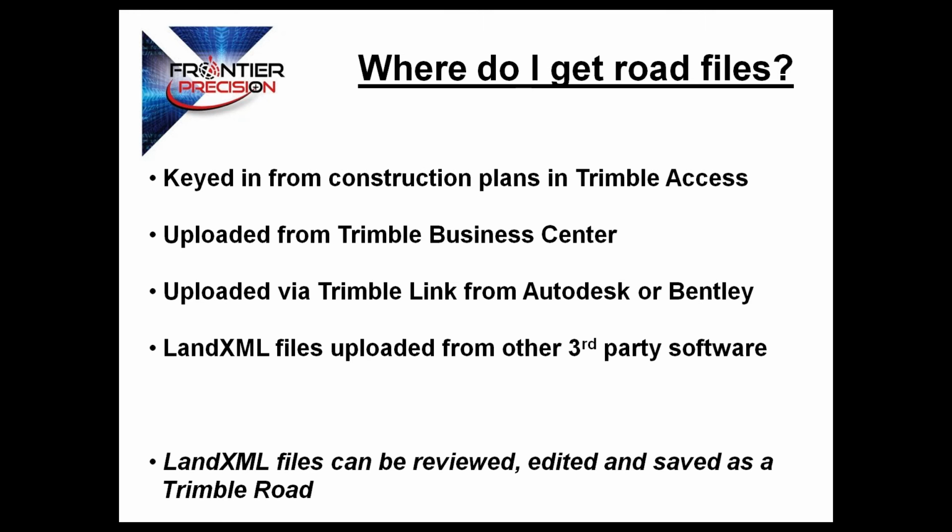Another little note on the bottom is land XML files can be reviewed and edited and then saved as a Trimble road in Trimble Access. So for example, from a CAD package, we can export a land XML file that contains multiple roads, and then we can extract and review or edit one of the roads from that file and then save it as a Trimble road to stake out in our software.